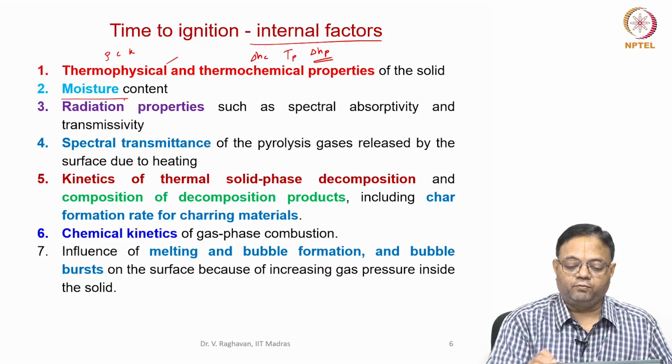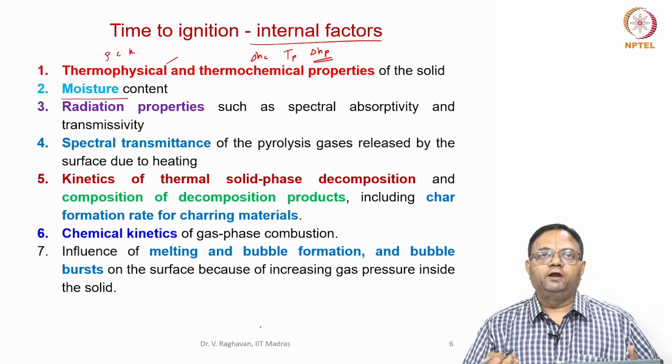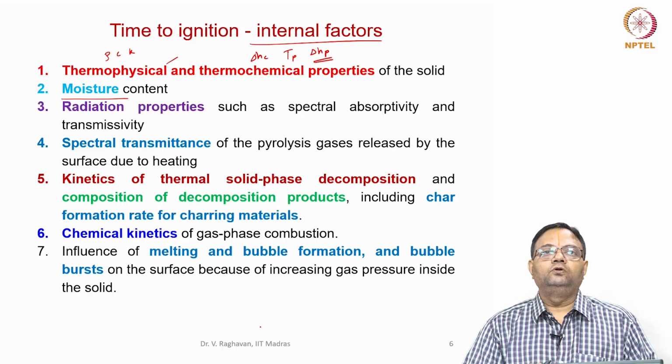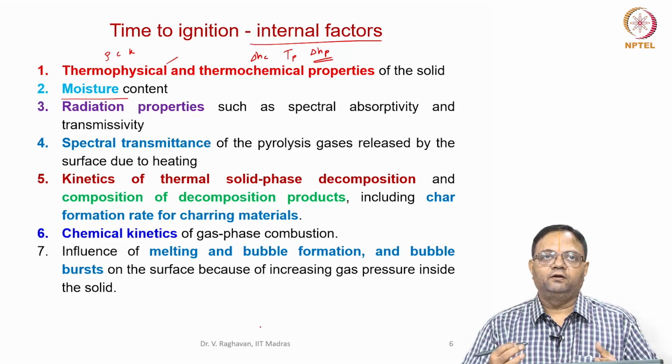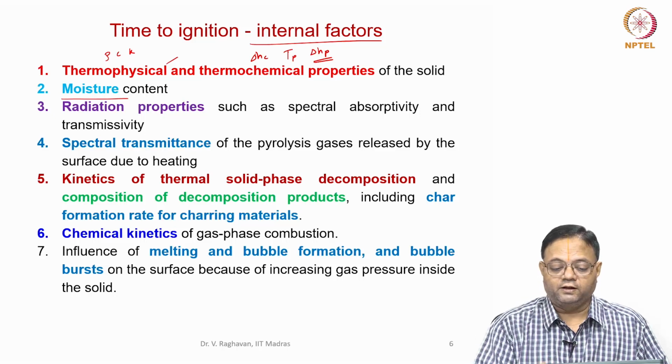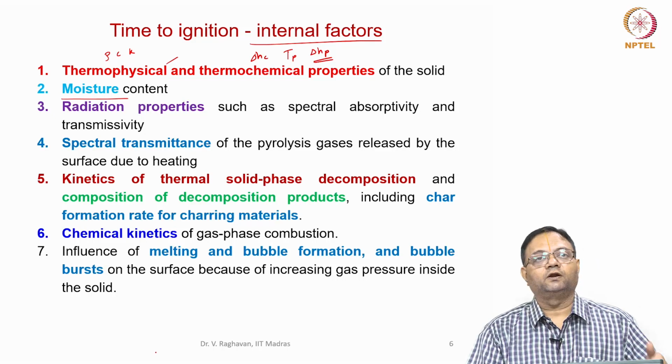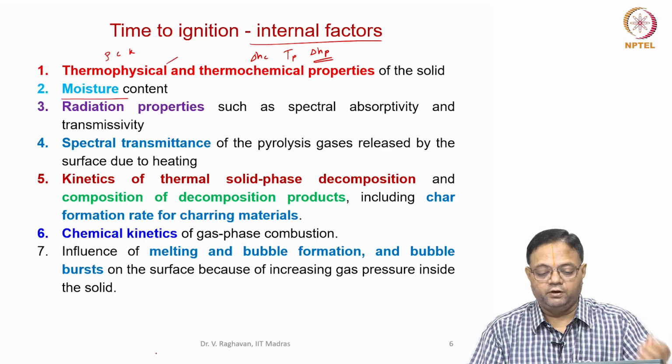Then moisture content. If the moisture content is higher, we need to supply the latent heat, or the temperature has to be increased to 100 degrees centigrade to remove the moisture. So this is another issue. If the moisture content is higher, then the time to ignition will increase.